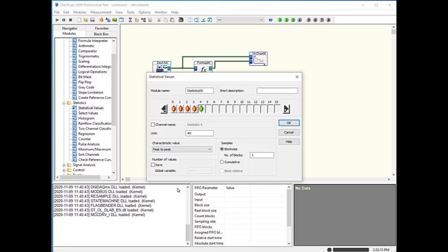This is a good time to name your channels because you've transformed them away from what they were originally. So we had the analog input, and now we're going to do statistics on the analog input. So on channel 0, I can give it a channel name. I can select and delete the value that's there, and I can do AIN 0 minimum. And then I can do this for each channel in turn.